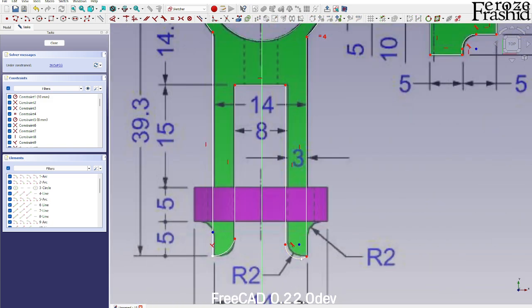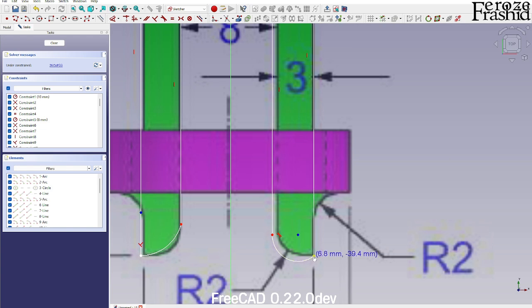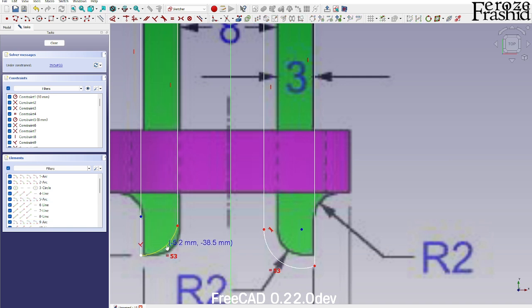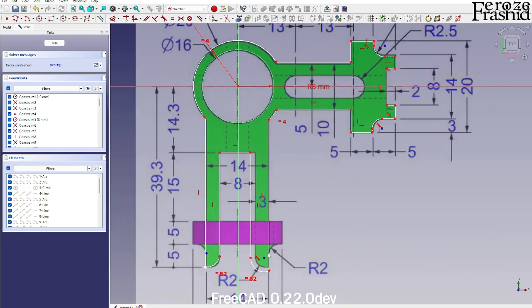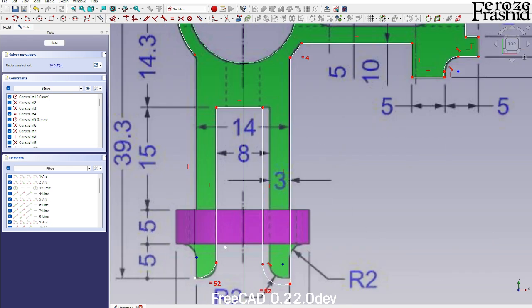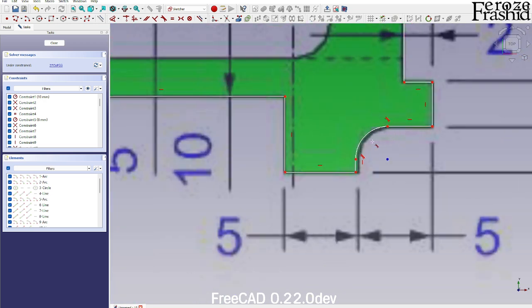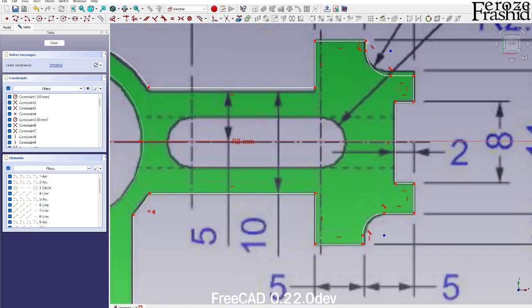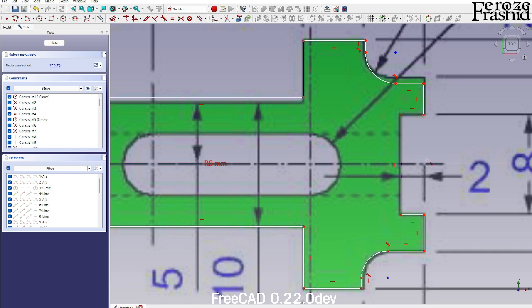And here, I see where these two will be equal. Okay. And I'll take this perpendicular out right now. If we need it, we'll do it later. Let's go ahead and take care of the tangencies. So that's T on the keyboard. I want to make these two tangent, and then all of these are tangent because of the polyline. Okay.